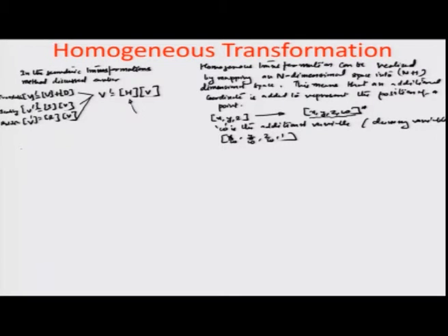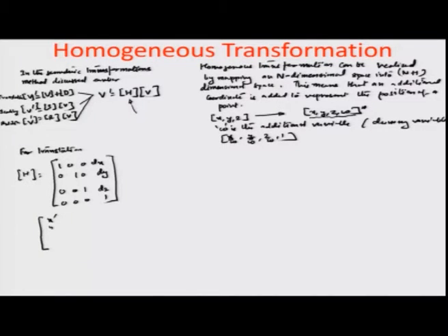So, for translation now we will be using a multiplier matrix, let us say the H matrix, which can be represented as 1 0 0 dx, 0 1 0 dy, 0 0 1 dz, 0 0 0 1, and let us see if this transformation happens. Well, let us actually just try to represent the addition matrix of the translation. Let us say a set of coordinates x dash, y dash, z dash and 1, the dummy coordinate, generated through multiplying the H matrix that we have just formulated